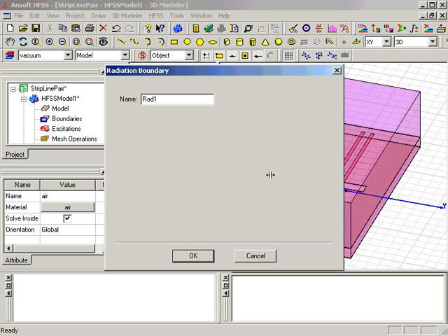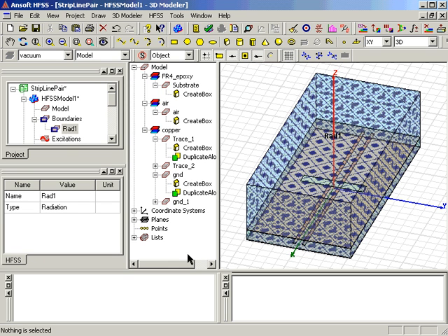We can use the object selection here since the bottom face is coincident with the ground conductor and is shielded by the perfectly conducting object. Otherwise, we could use face selection, select the 5 faces requiring the boundary, and assign radiation to only those faces.